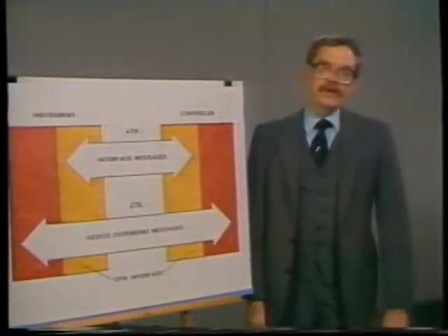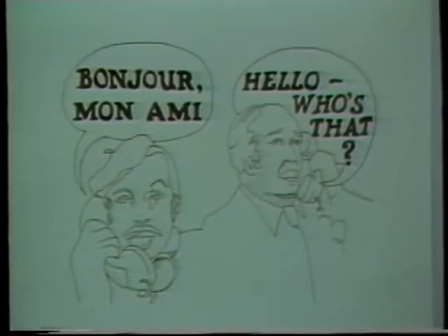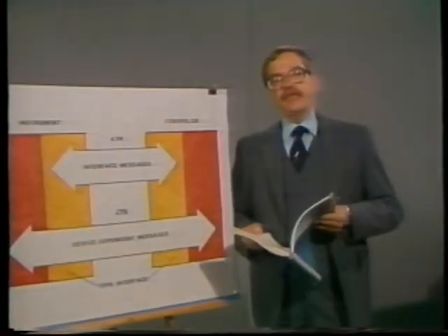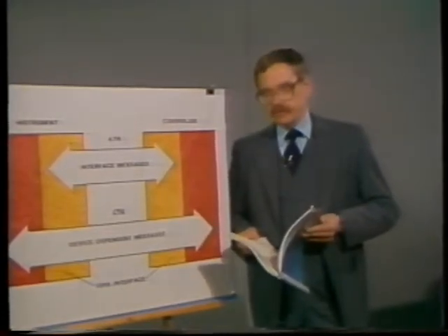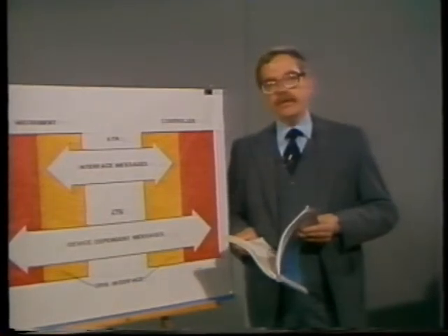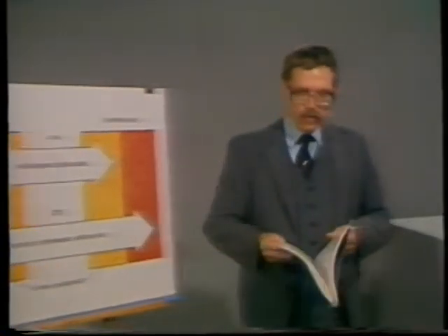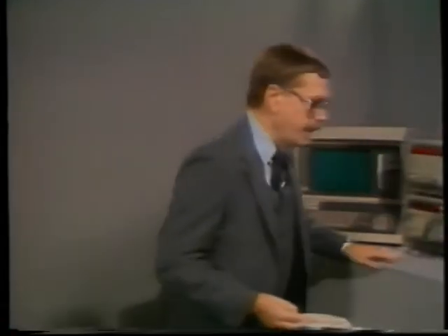A telephone system analogy is a good one. IEEE 488 compliance ensures a link from device to device, just as dialing the proper number ensures a connection between specific telephones. But if one user only speaks and understands English and the other only French, no communication will take place. Similarly, IEEE 488 compliance will connect two devices and handshake bytes between them, but the bytes may be totally meaningless to the listener. We'll talk more about this problem as we move beyond GPIB in a few moments.